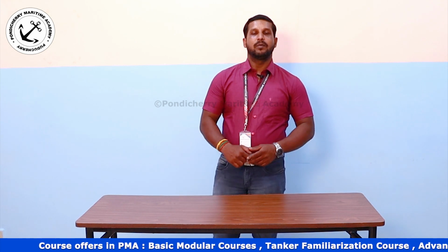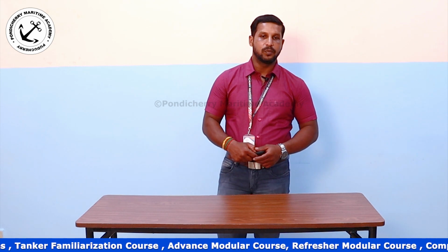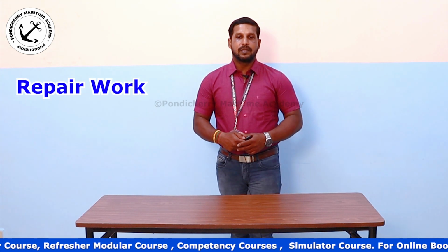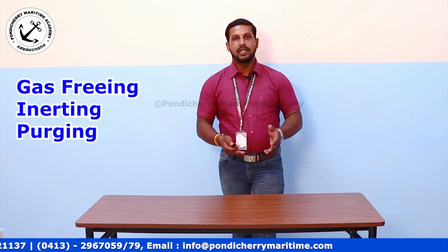It is important to evaluate the atmosphere of the cargo tank because of the following reasons, but not limited to: before entering any space for inspection or repair work, as it is an enclosed space. Basically, a cargo tank comes under an enclosed space. Before taking the ship to a dry dock or shipyard for any repair works, before gas freeing, inerting or purging operations to be done in the cargo tanks, before loading a new cargo in a tank, before crude oil washing or washing the cargo tanks.